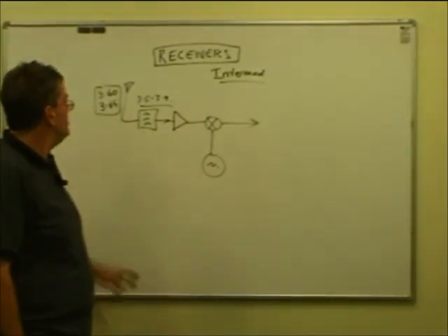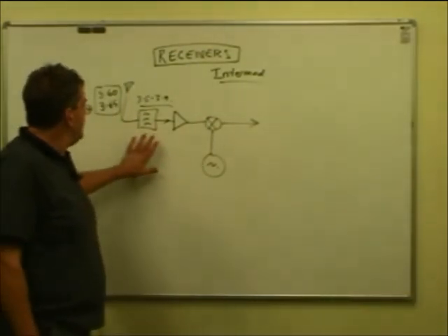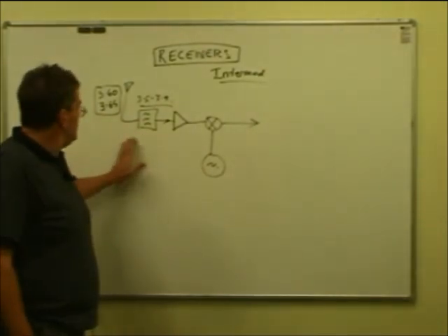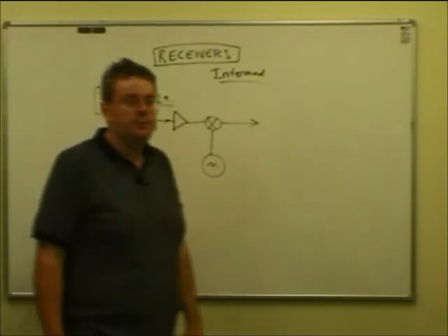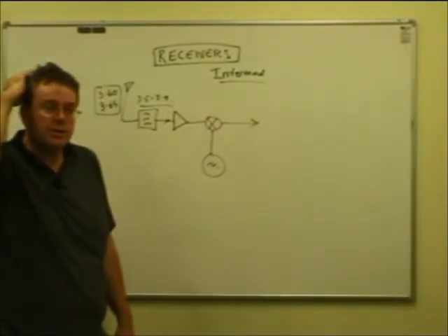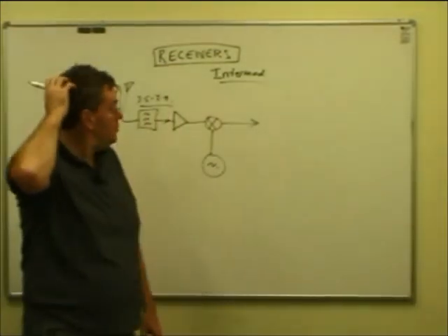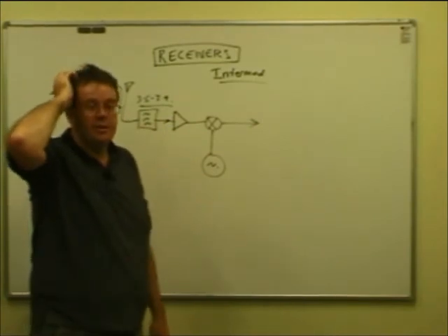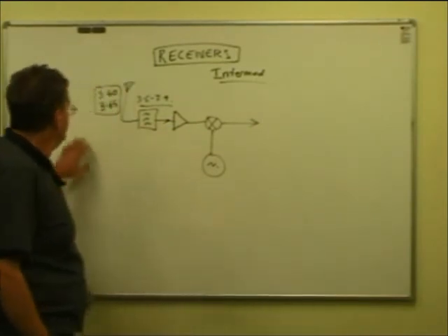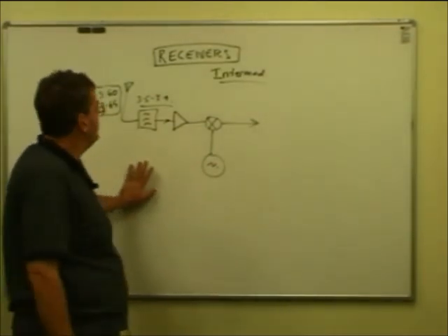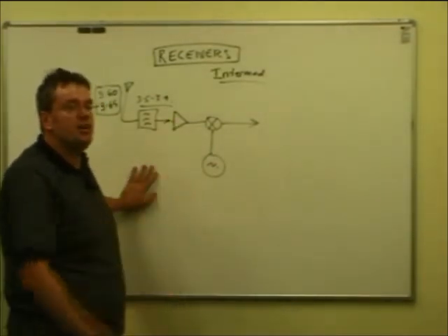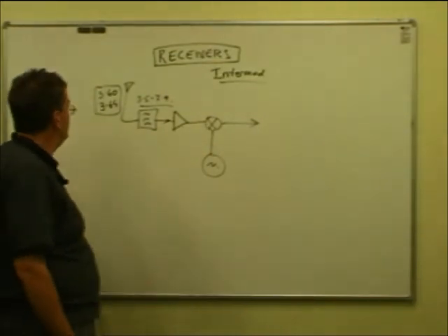We get this thing called intermodulation. It's when very strong signals pass through a system like this, they interact and create new signals. It happens in single sideband transmitters, and we're going to talk about that. It's called splatter when we come on to transmitters. It's a nasty phenomenon, and it's called intermodulation or intermod. It's also a major problem in amateur radio on repeater sites, where we've got lots of strong signals in close proximity.